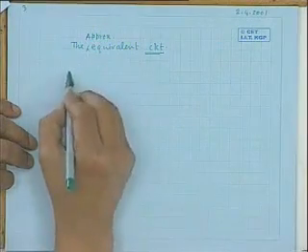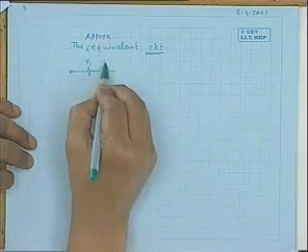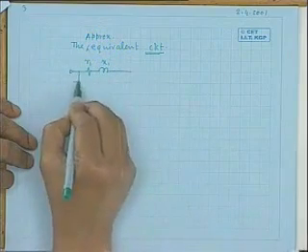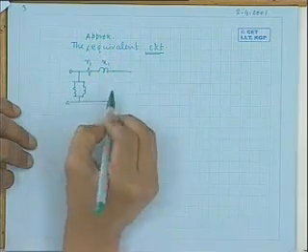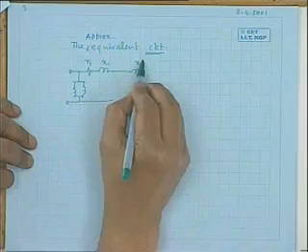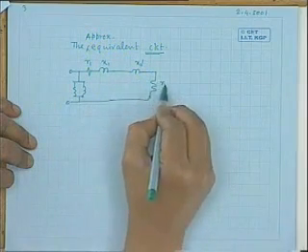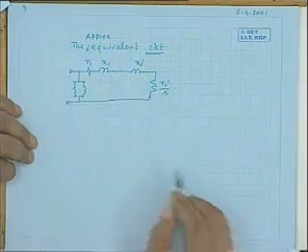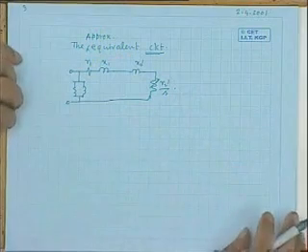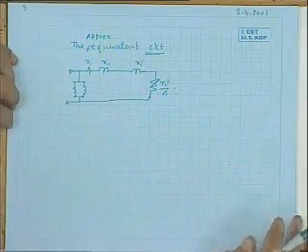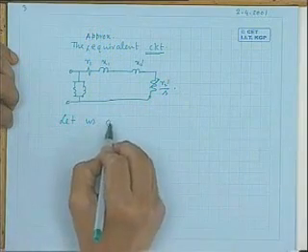The equivalent circuit will look like R1, X1, and this branch you bring it here, and here you write X2 dashed, and this resistance in the combined form I will write R2 dashed by S. This is the variable resistance. Next thing, another approximation I will do. Let us, for the first time, assume